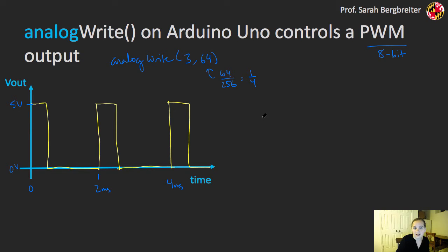Well, for this we actually have to cheat a little bit, and we add some external circuitry. In our case, we're going to add a low-pass filter. At the input of this filter, I have that PWM signal right there. And then at the output of this low-pass filter, I'm going to get an approximate analog output voltage based on the duty cycle of this PWM signal. And of course, that's assuming that I choose my R and C correctly to filter that.